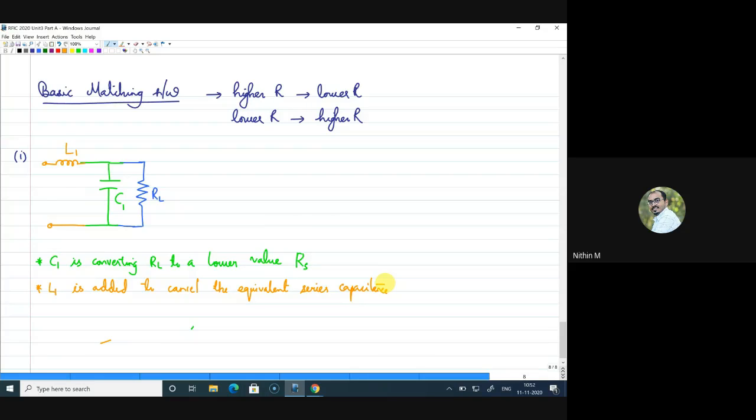So I can use an inductance, or why can't we place a parallel resistance? Okay, so how will you place a parallel resistance and transform the impedance? I didn't get that. Sir, from what I understood, you're just trying to reduce the impedance seen. Currently, it's RL. So if you placed another resistance in parallel, even if they're equal, the impedance would be RL by 2. Oh, okay, okay. Then I think now Saurabh's question is valid.